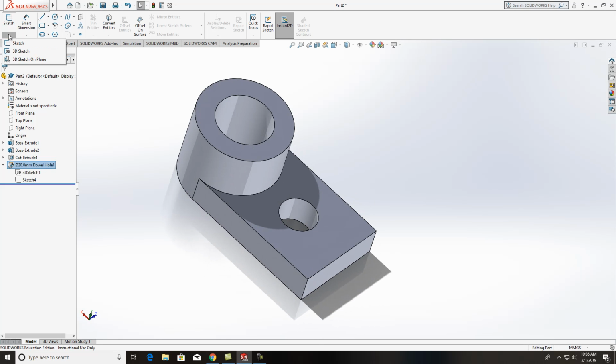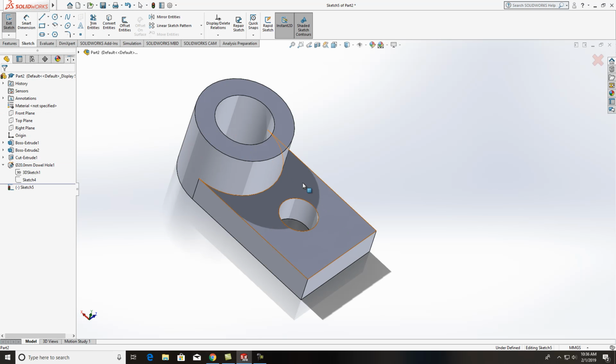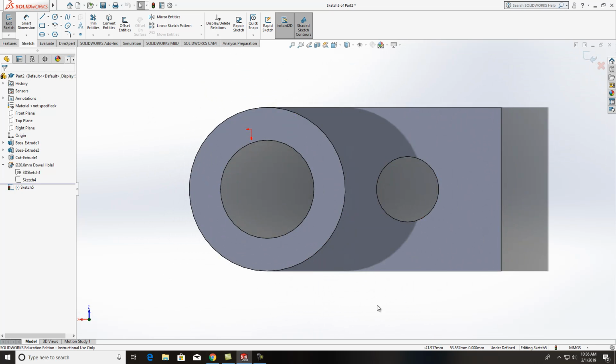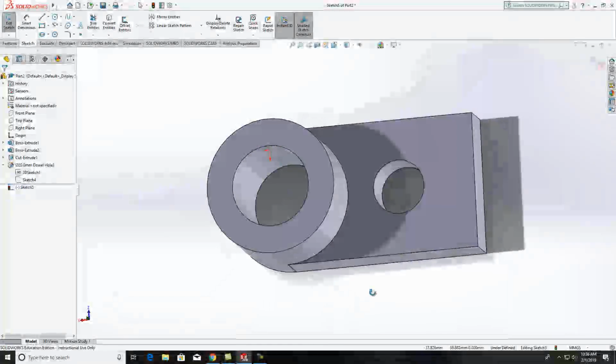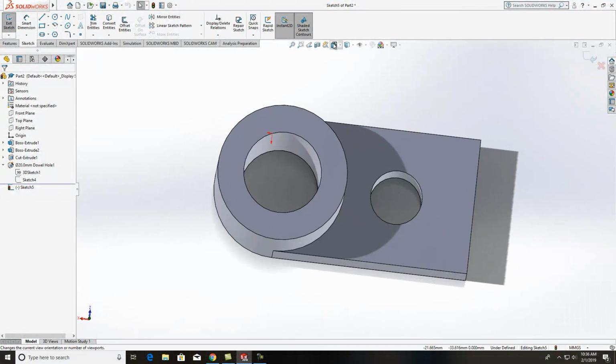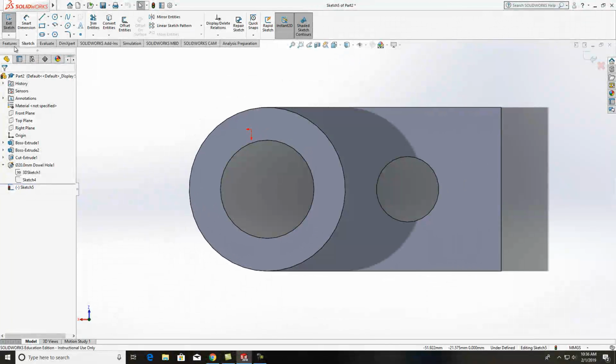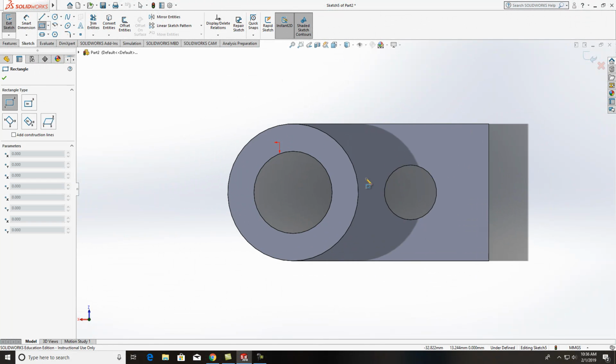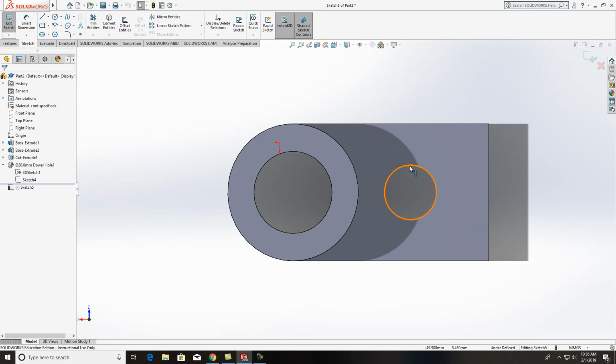Just go back into your standard sketch, click on the face of that, and I want to turn it around so I can see it. So I click on that just like that, and see, if you're used to some of these softwares of holding the button down and panning, that'll happen to you. So I just click back on that, click that face, and then I'm going to take and I want to click on my rectangle, and I click up there in the top quadrant of that.